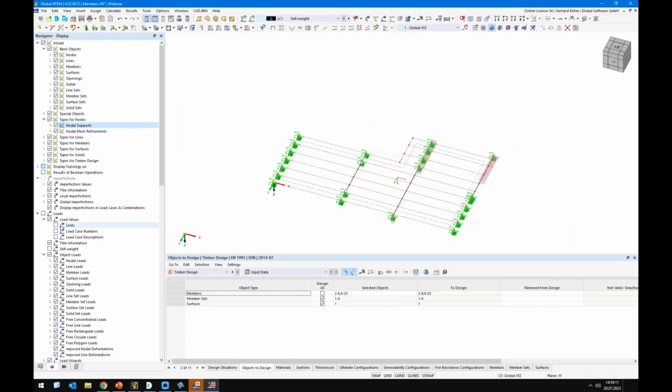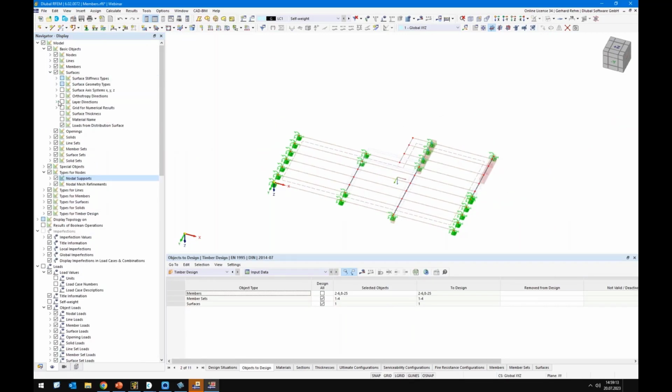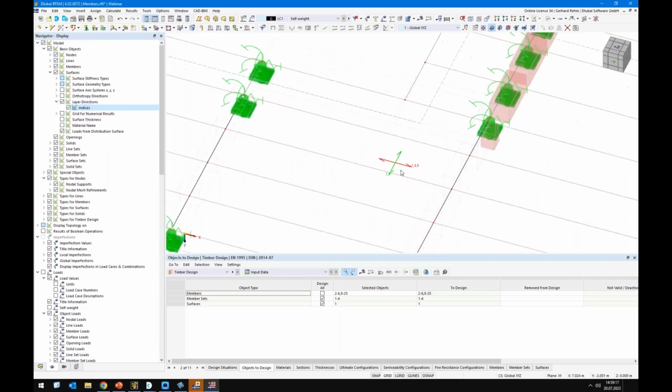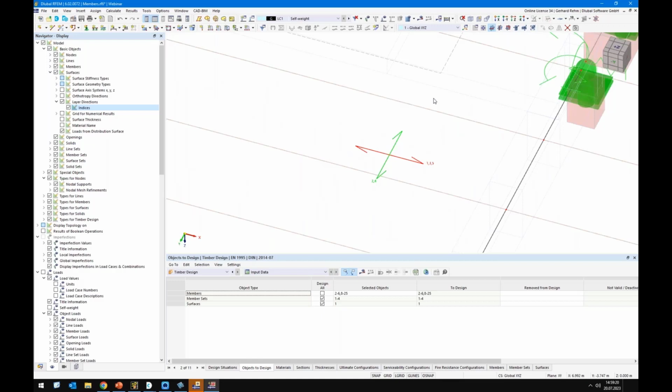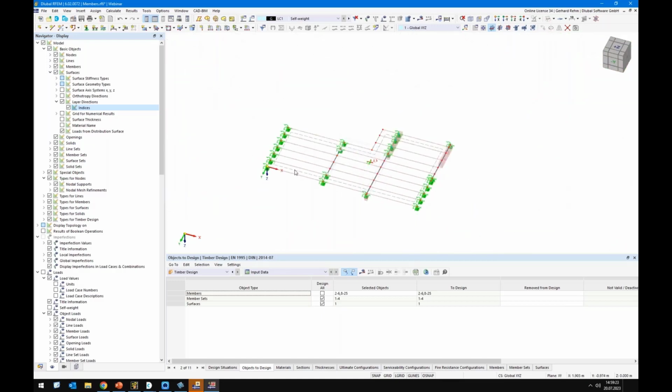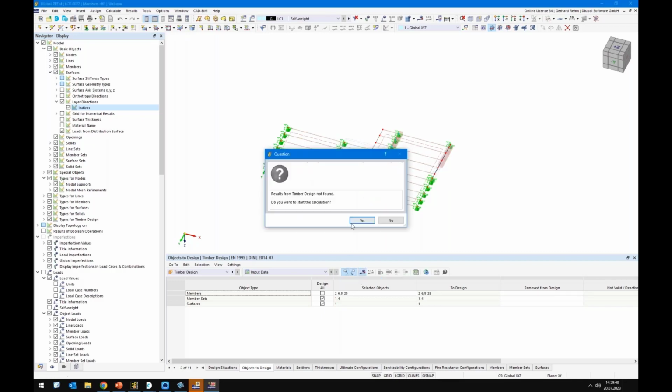We can check the orientations again for this surface in X and Y direction. So layer 1, 3, and 5 goes in this direction, and layer 2 and 4 in this direction. So it's okay. Here it's the same because of the bending moment. Of course, the elements are larger. Maybe it's worth to model the surface, to split the model at every, in this case, it's 125 centimeters, and add a line hinge in between. So for simplification, I leave this for now.